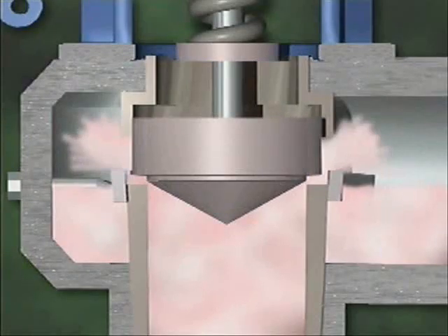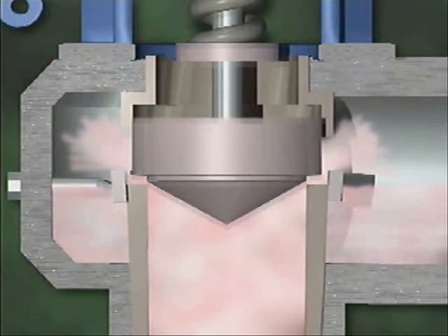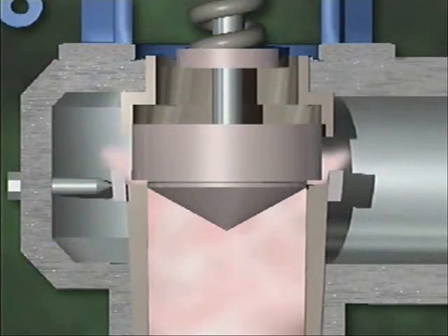As pressure decreases, the velocity of the escaping fluid also decreases. Spring tension begins to take over, pushing the disc down. The spring tension in a safety valve is preset, and it must be correct for the valve to operate properly. When the system pressure drops to the point where the valve popped open, 1,000 psi in this case, the valve doesn't close, because the lip of the disc is still exposed to the pressure and velocity of the escaping fluid.